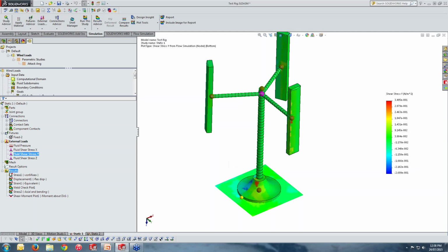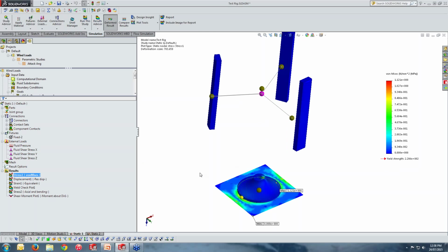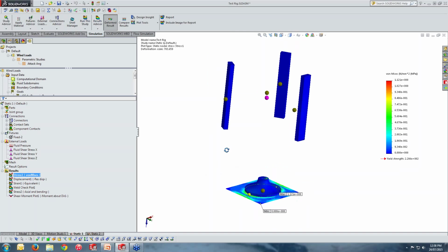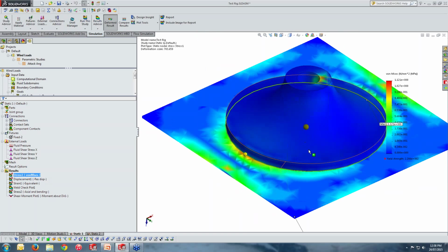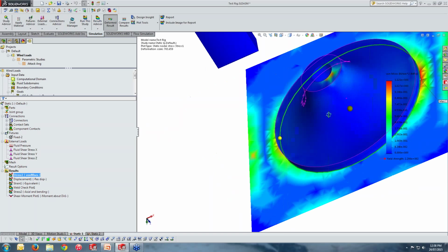Second, you go to your results section. So you can simply review the stress values on, let's say, the solid part. Well, obviously it's showing us much less than the yield strength, showing us some stress concentration on those locations.